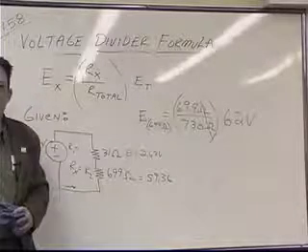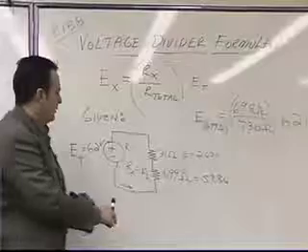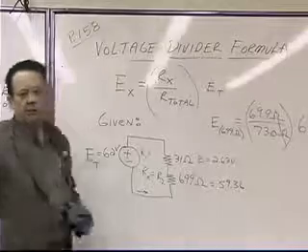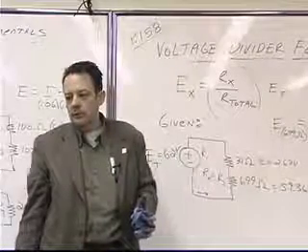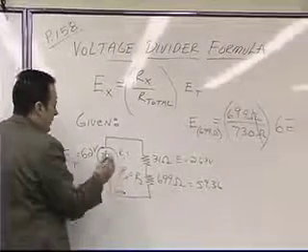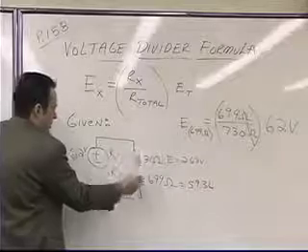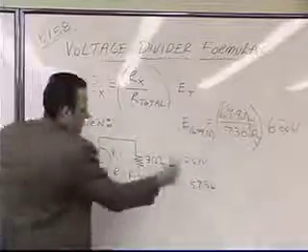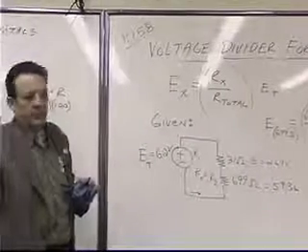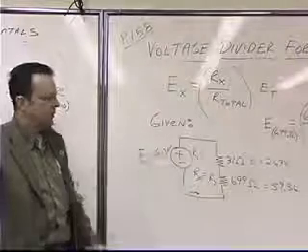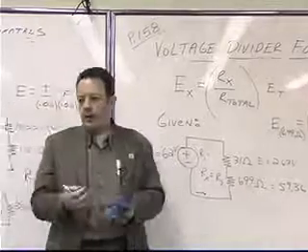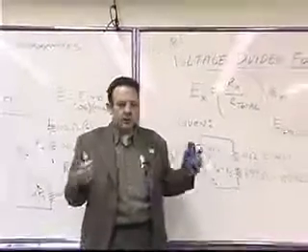Now, is it fair to say that this is a closed loop? Does Kirchhoff's voltage law have to apply to a closed loop? Yes. Okay. So is it true then that this voltage must be equal to this drop plus this drop? Yes. Okay. What's this drop plus this drop? 62. Pretty darn close to 62 if we take into account our rounding errors. So thus we have verified Kirchhoff's voltage law like 3 different ways.